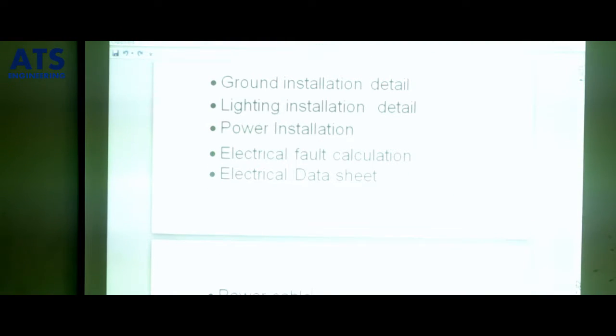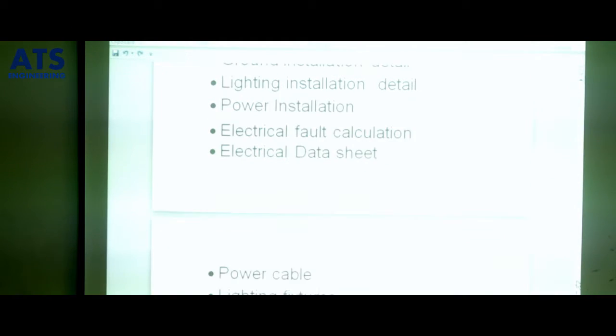We have different ways of doing projects. We have conceptual engineering. We have field engineering, which is called front-end engineering. We have detail engineering. In detail engineering, we do all the details. In terms of our drawing, we do detailed drawing and we study data sheet. We do calculation ranging from cables to lighting to UPS and all electrical equipment. We do sizing calculation for them.